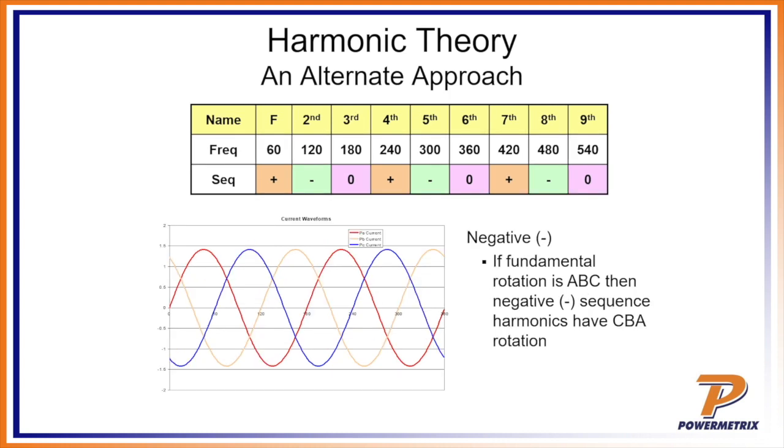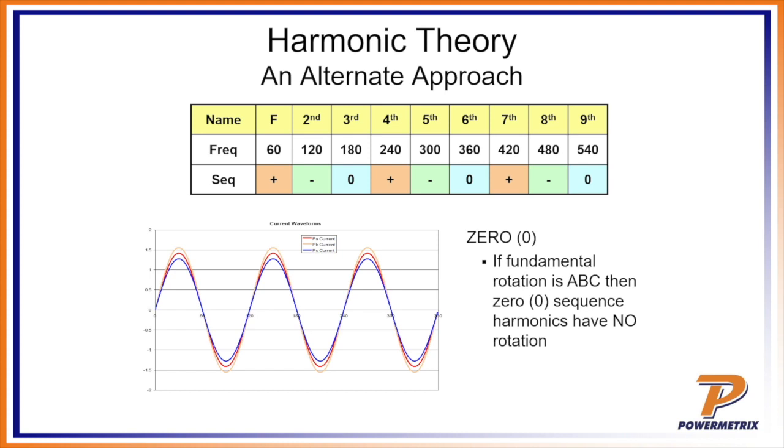If we talk about our negative sequence harmonics, that's having the opposite effect. It's actually trying to slow that motor down, trying to pull it back. So once again, think of that generating friction, generating heat, and so that's a problem. Those are both bad, but really the real culprit are the zero sequence harmonics. Those are also known as thirds or triplets.